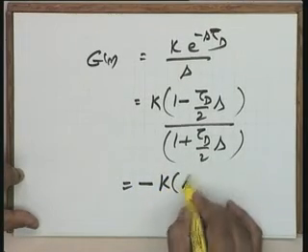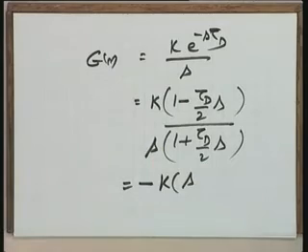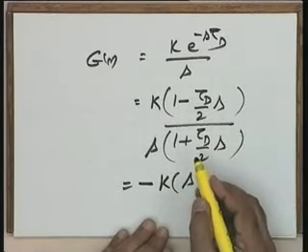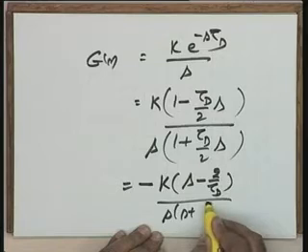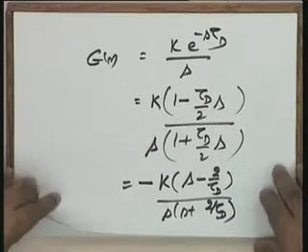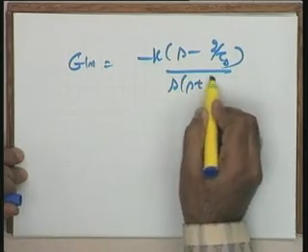Now if you see your pole-zero pair, this can be written as minus k by s. Yes, naturally the pole is there. Yes, this is the function now. Now you see that bringing it in the standard pole-zero form, I can write this as s minus 2 by tau d divided by s into s plus 2 by tau d. You will please note the interesting feature in this particular case is the following. Your G(s) is equal to minus k times (s minus 2 by tau d) divided by s into (s plus 2 by tau d).